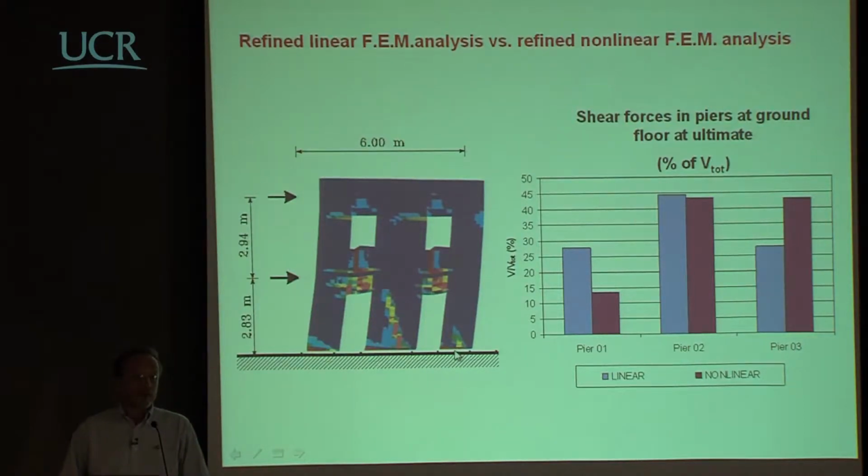There are several reasons, but a main one is that when you go into a nonlinear response, you take into consideration the fact that when you are pushing in this direction, this wall is going to have a much higher compression force, and this wall a much lower compression force. Due to this effect, the response of this part here and of this part here, that in other structures are similar, in the case of masonry can be quite different.